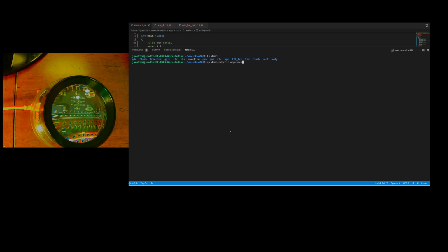And I hope at some point they'll get a PlatformIO setup for the compiler tools for this, like they do for things like the ESP32 and other ESP things like that. And they may even do an Arduino wrapper for it. There's a good bit of code they'll have to do for wrapping the HAL functions to make them look like the Wiring stuff.